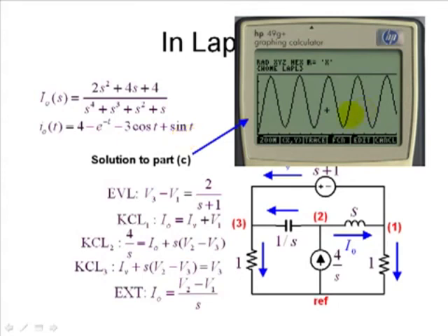How that current in the inductor oscillates between 1 amp and 7 amps permanently after an initial transient period dictated by the time constant of this exponential. After 5 seconds, the steady state is a sinusoid with a frequency of 1 radians per second according to that oscillates between 1 amp and 7 amps. That is the current in there.